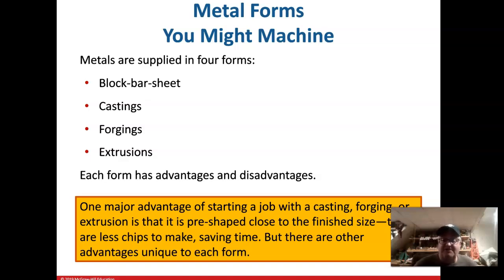If you go to a job shop or machine shop like what I'm used to, where I served my apprenticeship, you're going to be using a lot of bar stock, a lot of high-speed steels, a lot of tool steel, maybe even aluminum, where you're turning that part and you're really concerned with maximum material removal, trying to get that material off of that bar and into the shape that you need it to be as quickly and as fast as possible.